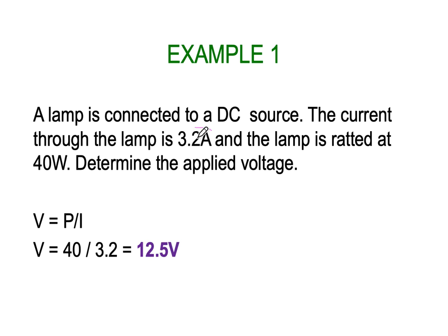At the end of the day, here's the data, amps and watts, and we've been asked to find voltage. So what equation does that? It's just a matter of looking at your equations and finding the one that has those three elements and transposing it if you need to, or maybe it's already in the correct form.